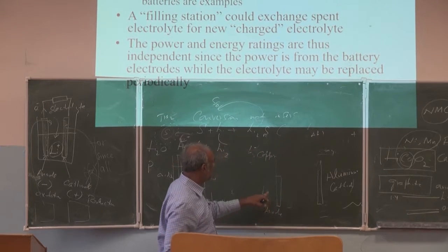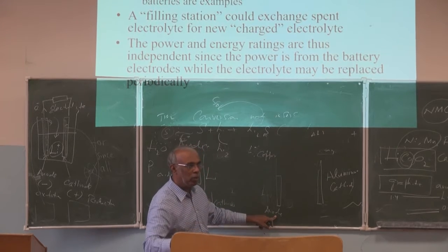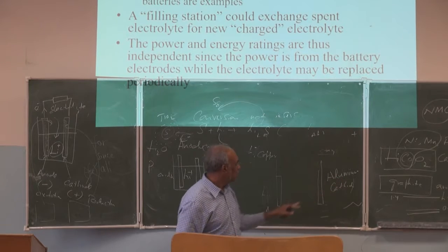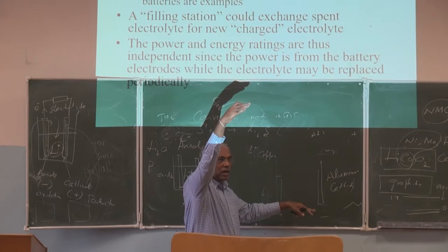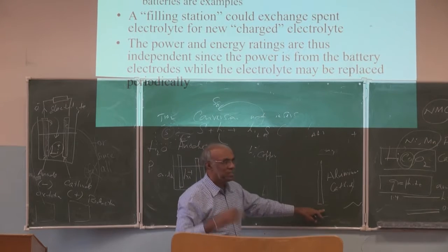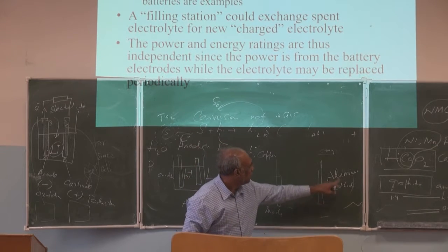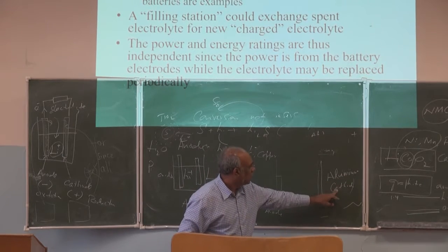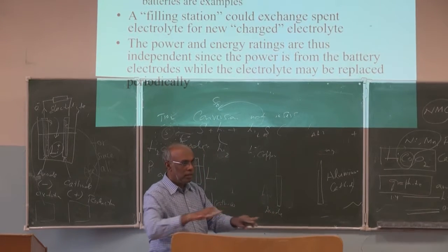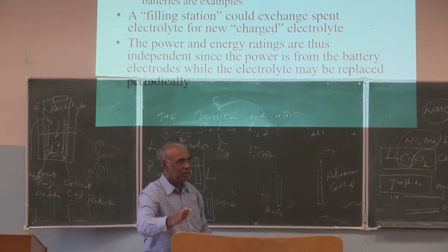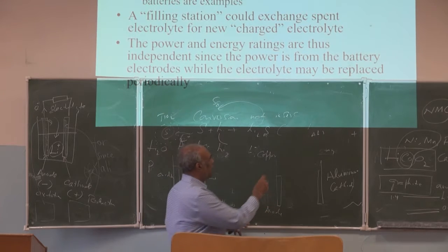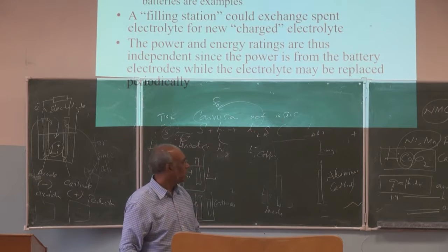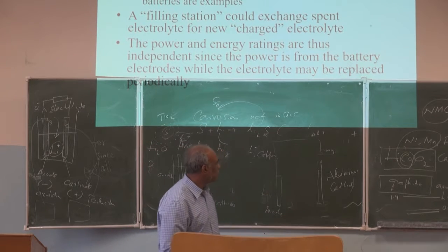The reason is that anode potentials are very low, right? At low potential, aluminum can get oxidized. The cathode works at high potential, so copper gets oxidized at high potential. So that's why typically we coat the cathode on aluminum and cast the anode on copper. Then we can take the current out, right? So that's how, if you look at any battery, anode and cathode are done.